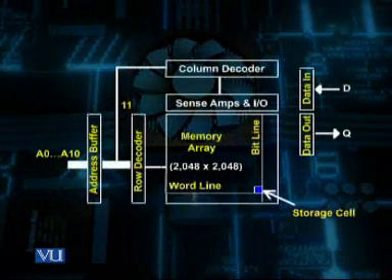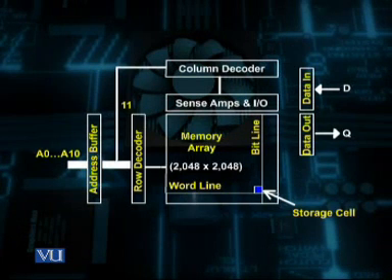However, inside the chip, we use a multiplexer-demultiplexer circuit so that the number of pins may be reduced at the periphery of the chip. The row decoder shown here affects the latency, while the column decoder affects the overall bandwidth of the memory. Internally, it might use banks of memory arrays.